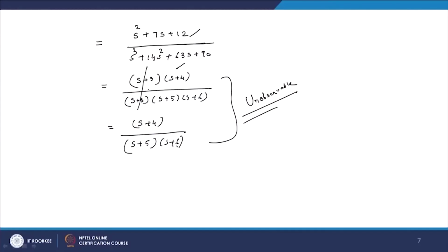This can also be tested by using this Kalman form. So any of them can be used, but here we will find that if there is a pole zero cancellation, the system itself is unobservable, and here this s plus 3 and s plus 3, this particular state is not available for the measurement, because in state space design or actual practice, we have to design a controller.